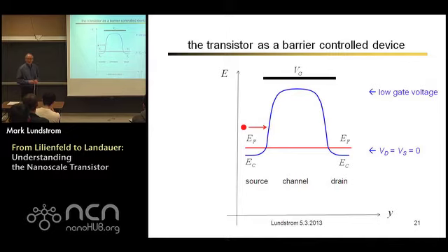And an electron can't flow because there's this big energy barrier that stops it from flowing from the source to the drain. Right? It's stuck. Current is zero. But we remember that if we start applying some biases, that potential energy is minus Q times electrostatic potential. So if I apply a positive potential, I can lower energies. That's how we make a transistor.